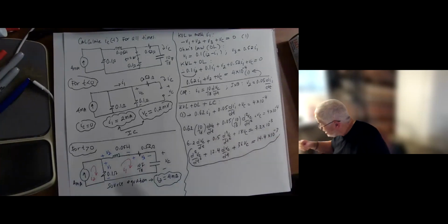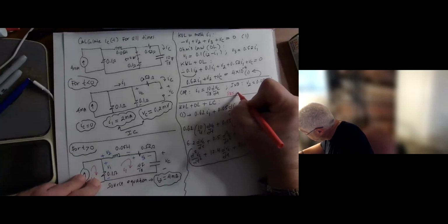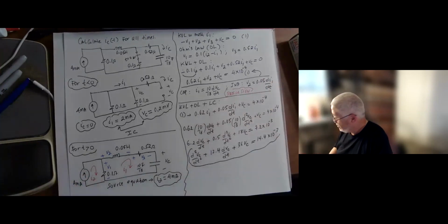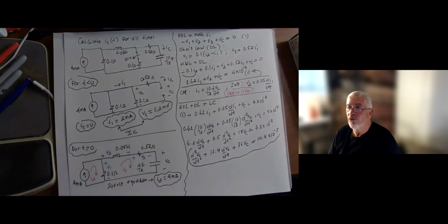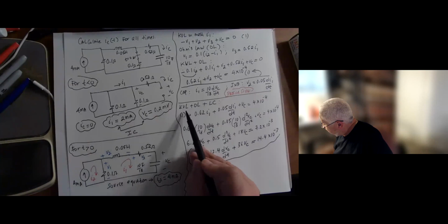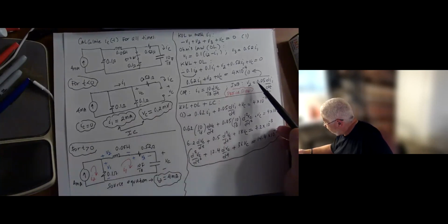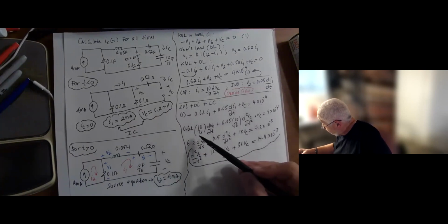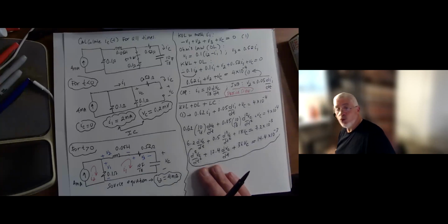When I do this thing here, you need to be mindful of the passive sign convention, because remember, these elements are passive elements, okay? You need to be mindful of the passive sign convention. That is the current entering the voltage on the positive terminal. So we write this. And then now this step is KVL plus Ohm's law plus bringing the inductor and the capacitor. I bring the inductor first, and then I bring the capacitor, and that picks up a second order derivative there. And then the last step is to normalize.